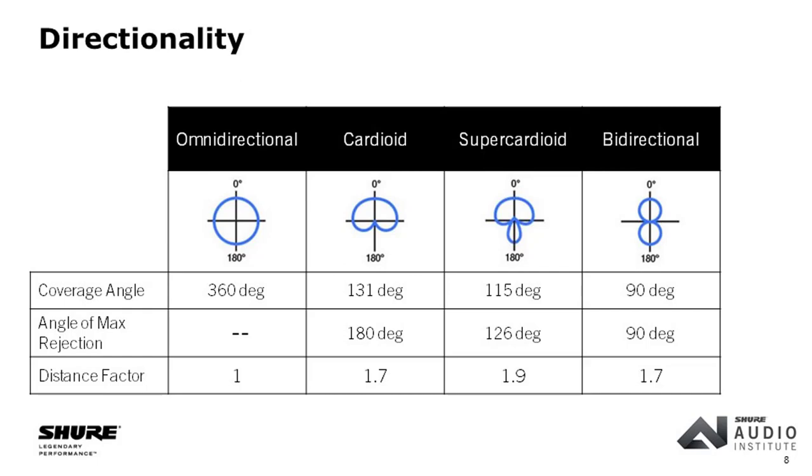That brings in another concept, another misconception about microphones, which is that a directional microphone will somehow reach out to the sound and bring it closer to you. People will ask, what's the reach of this microphone? Microphones don't have reach. They have something called sensitivity, which we'll talk about in a minute, but that's how sensitive it is to varying levels of sound. The more sensitive the microphone, the better job it can do of picking up weaker sounds. But the further away you put the microphone, the more it's going to pick up that room sound. And we have some further illustrations of this later on. But the distance factor is a way you can help decide how far away you can put a microphone.